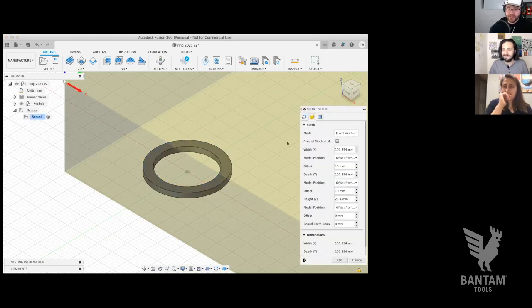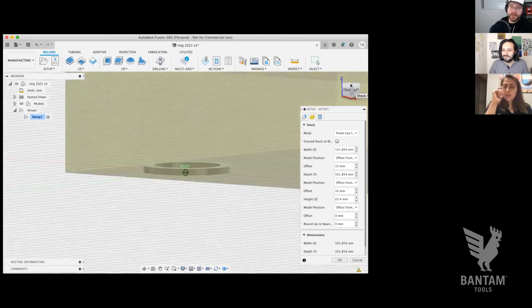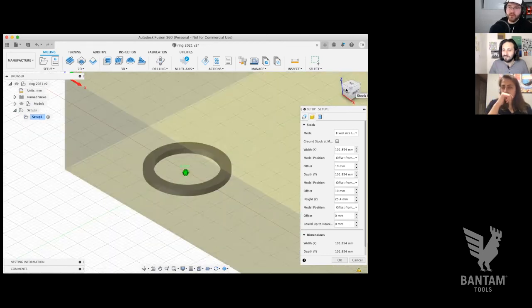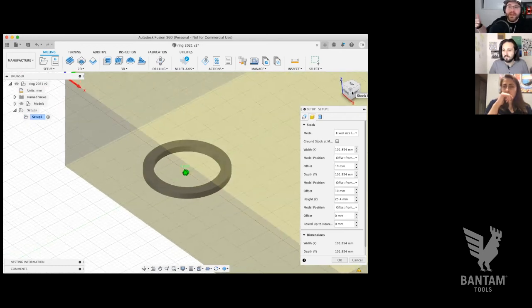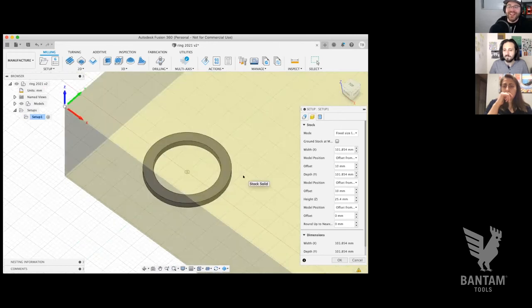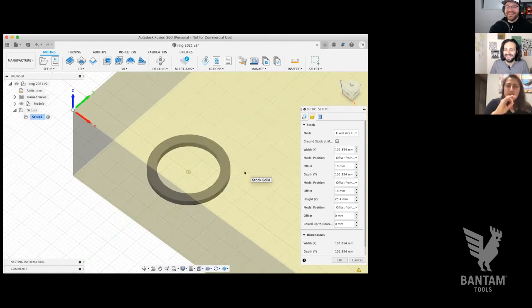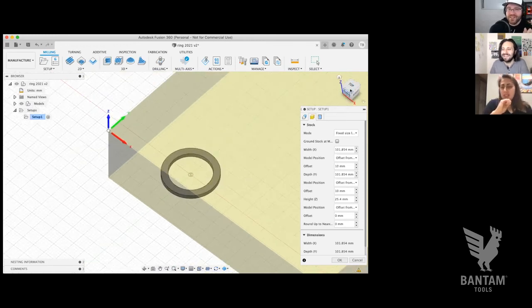Great. And then I do want to go back, and you're going to get really good at going back into this because I want to point out one more thing, which is round up to the nearest. When you were going through, you removed that, which is the right instinct, because we don't want to round at all. We're measuring things. So what's the point in rounding? So you can just set round up to the nearest at 0. This is good for our workflow.